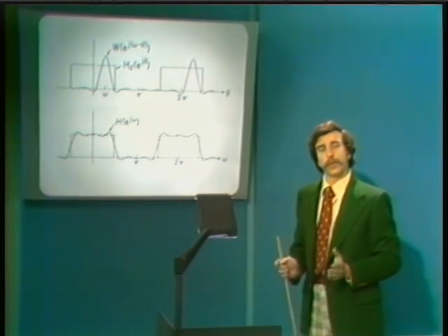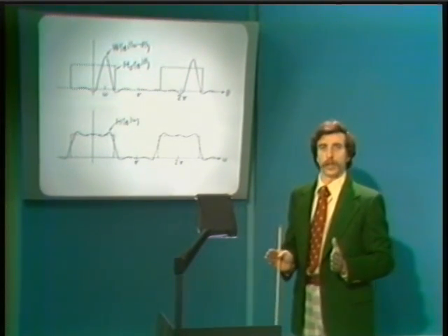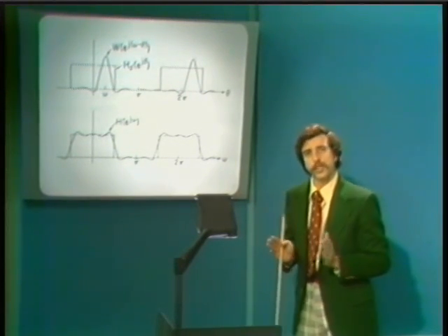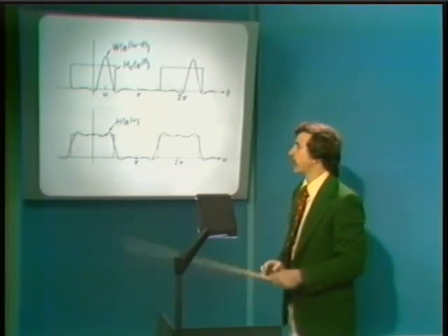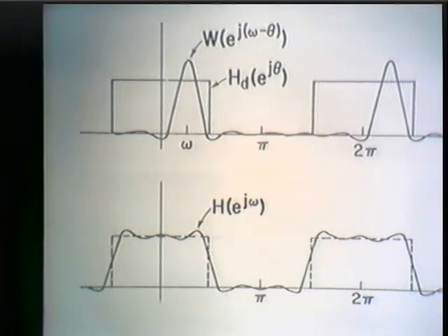So, in fact, as we try to make the time window, w[n], or equivalently the order of the finite impulse response filter, smaller, the tendency will be toward a widening transition band in the frequency response of the filter. Likewise, as we allow the order of the filter to get longer, we have more flexibility in the filter, and consequently, we're able to better control the transition band and the overshoot in both the pass band and the stop band.